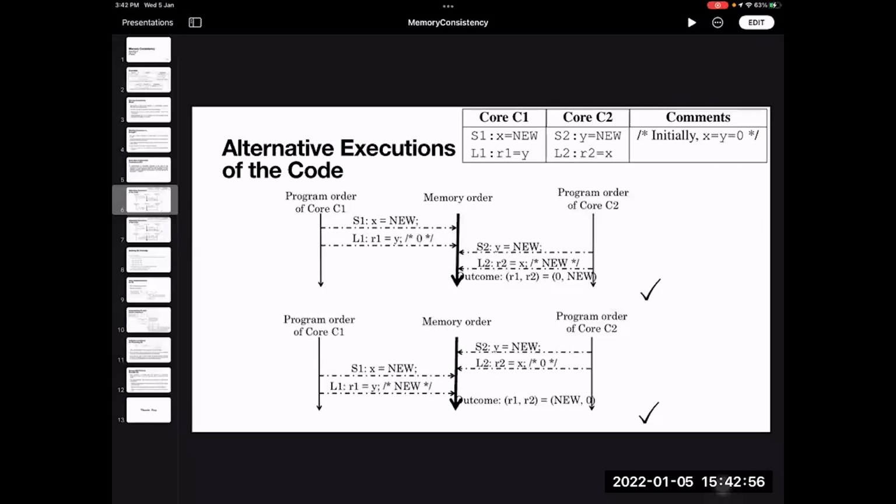Now different threads running on different cores will see different values. And that is actually going to create a problem. That is where, when you say sequential consistency, you disable the store buffers completely. But once you disable the store buffers, the stores have to be performed before any load, and that degrades the performance from the architecture point of view. That's what we discussed in the morning.